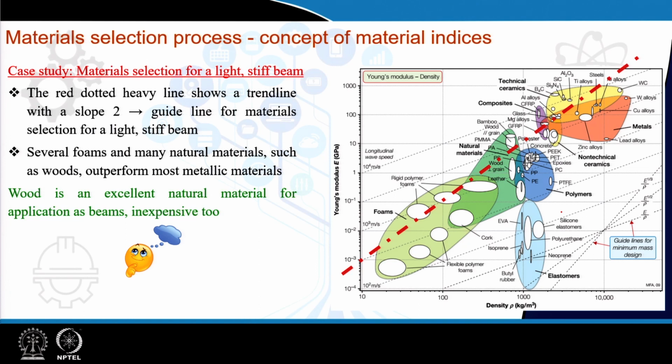As you already know, this kind of material property chart is very attractive because it allows plotting all the materials known in one single plot, and because these plots are log, that means both y axis and x axis are logarithmic in nature, we can have a very wide range of properties. As you can see in this plot, we have all the materials, Young's modulus against density, and we see that wood covers this middle portion, this pseudo triangular region, which are the natural regions for wood.